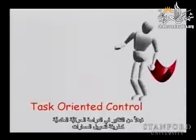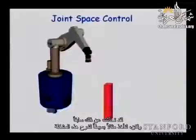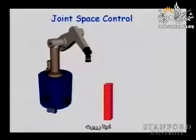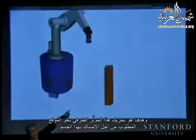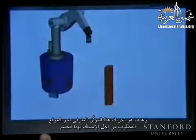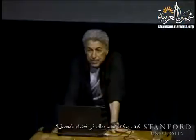where instead of thinking about the inverse kinematics as a way to transform the trajectories, we go directly to controlling the task. And I talked about this earlier, but let's take a simple example to illustrate this problem. So here is a robot, a mobile manipulation platform, and our goal is to move this robot end effector to this goal position to grasp this object. So how do you do that in joint space control?